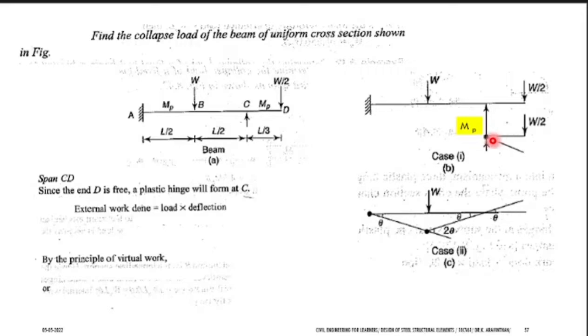Now you have a triangle. If you keep on adding the load, what will happen? This beam will deflect up to this much, and at a certain point it will break at the support. Now how to find this distance? The same formula which you used for the previous problem. How to find the height of the triangle? Take this as a triangle. What is the base? Base is L by 3. So this is known. How to find the height?